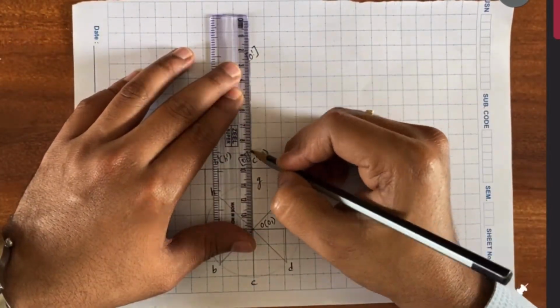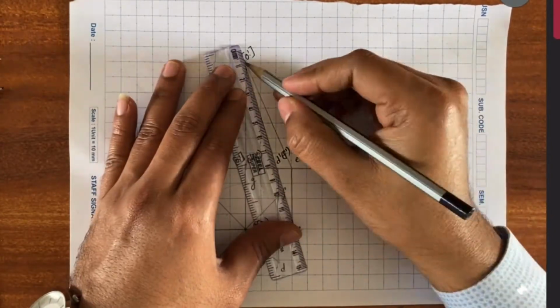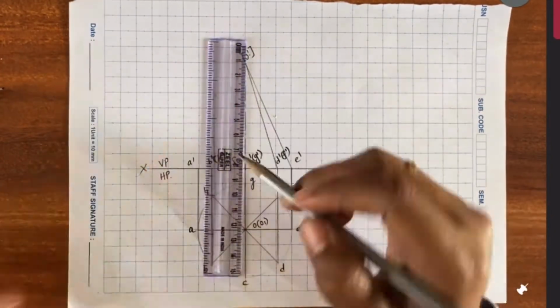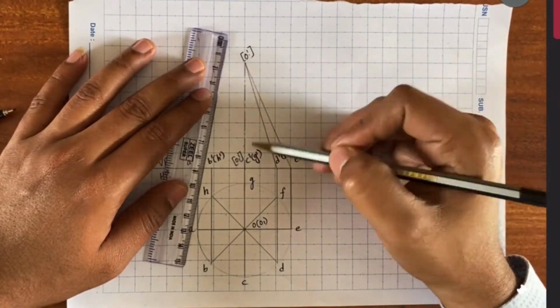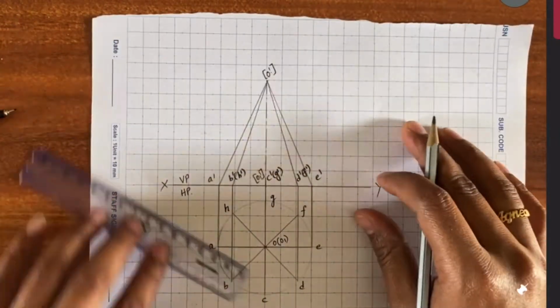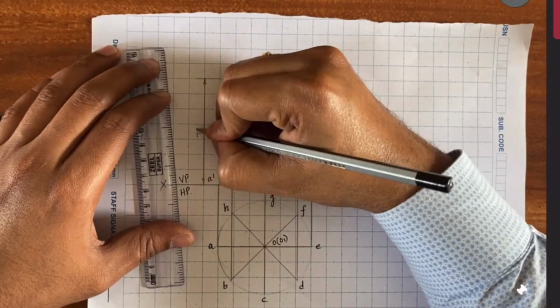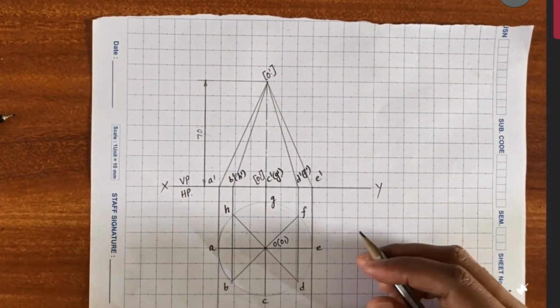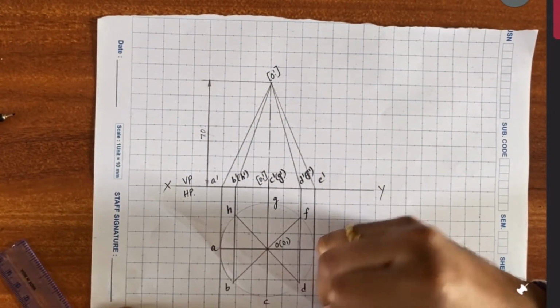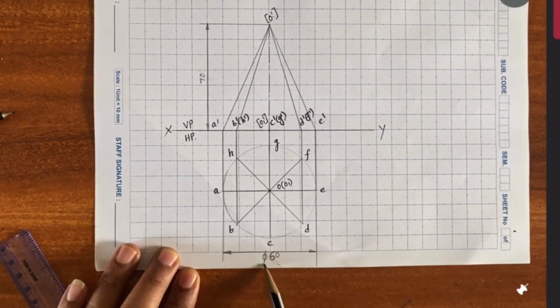The axis line has to be drawn with one longer and one shorter line. The front view of a cone will look like a triangle. The preference has to be given for the axis line, not for the projection line. So all these lines are drawn with thin lines, while the dark lines will be drawn with a pen, which I'll show you at the end of the video. Mention the diameter and the height.